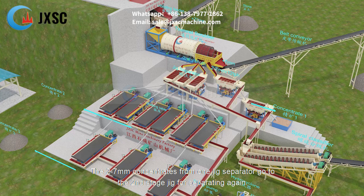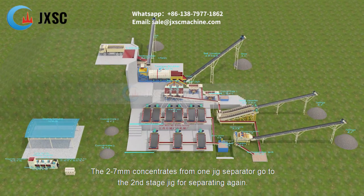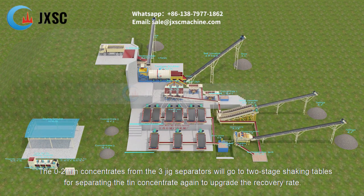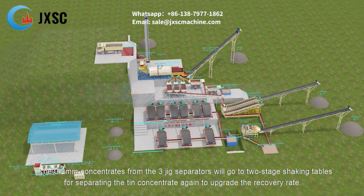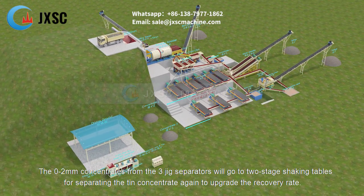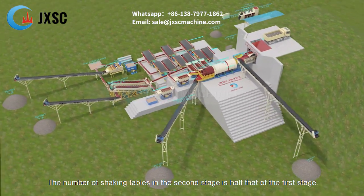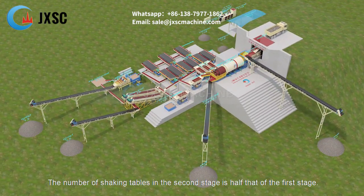The 2 to 7 mm concentrates from one jig separator go to the second stage jig for separating again. The 0 to 2 mm concentrates from the 3 jig separators will go to 2-stage shaking tables for separating the tin concentrate again to upgrade the recovery rate. The number of shaking tables in the second stage is half that of the first stage.